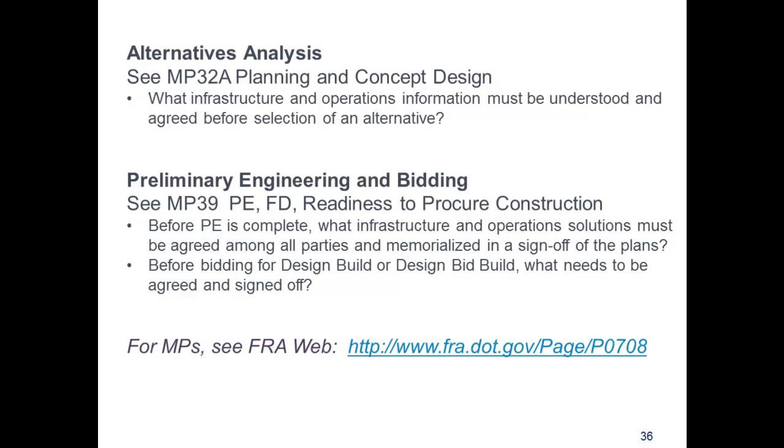Also in the document are sequencing plans and a construction schedule that integrates the track and signal modifications into the operating railroad. All of these documents include the construction staging needed to include in the upfront agreement, the sign-off package with all the parties. The sign-off indicates understanding that if a party subsequently decides they absolutely have to have a change, fine, they will pay the full cost of that change. Only after all this is done do you embark on final design.